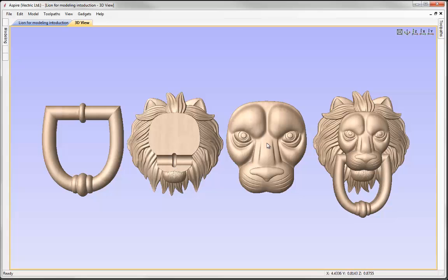We'll then model the face shapes, and ultimately the face shape is going to sit on top of the base shapes using the keyway. Now, as you saw in the concepts and theory presentation video, how that keyway works. So we're going to create a pocket on top of the base shape, a female version of the pocket on the underside of the face shape so that the two can slot together.